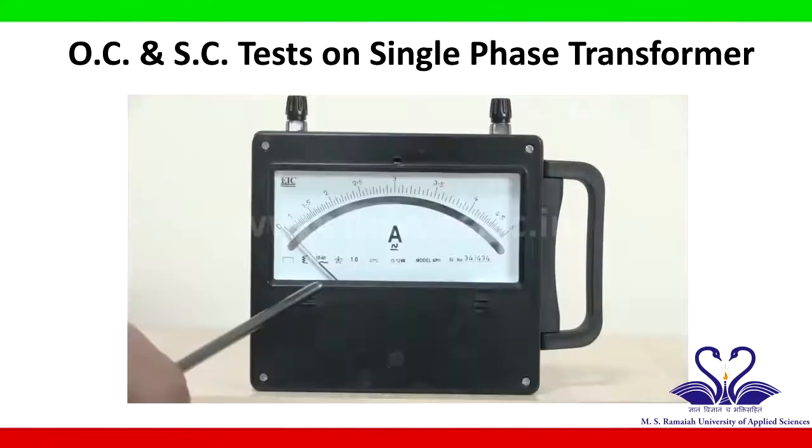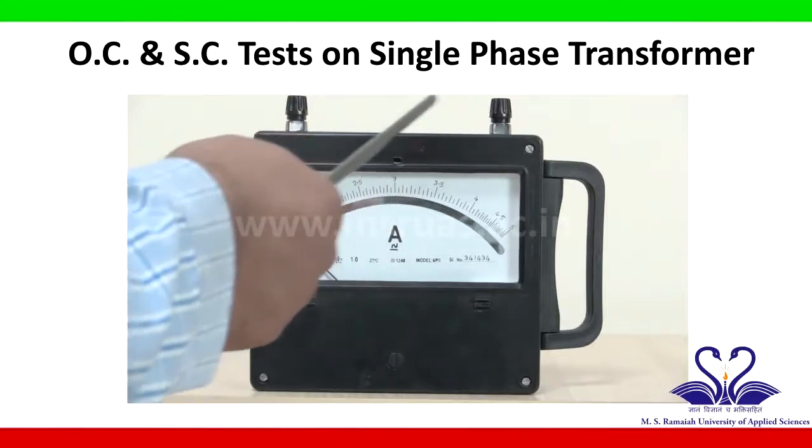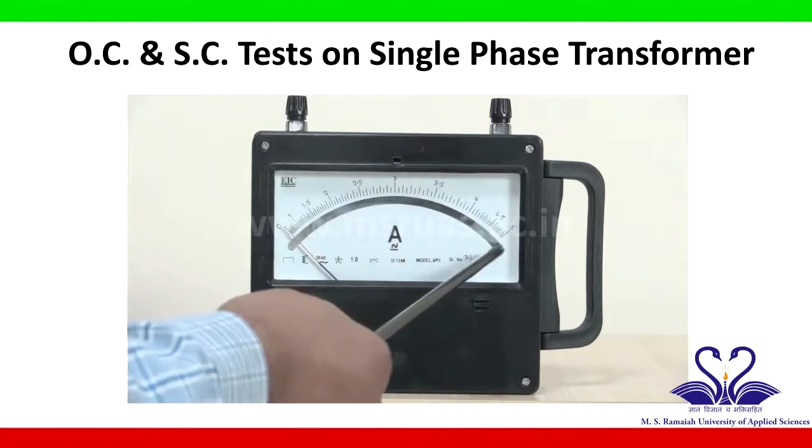This instrument is ammeter. Ammeter is basically used to measure current. Ammeter has two terminals. These two terminals are always connected in series with the circuit. Ammeters are available in various ranges. This particular ammeter ranges from 0 amps to 5 amps.